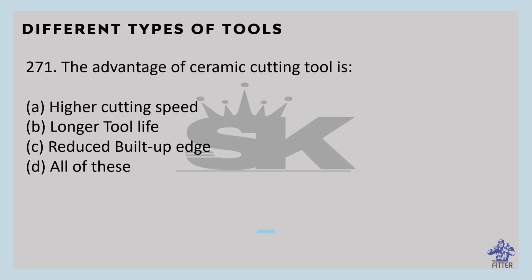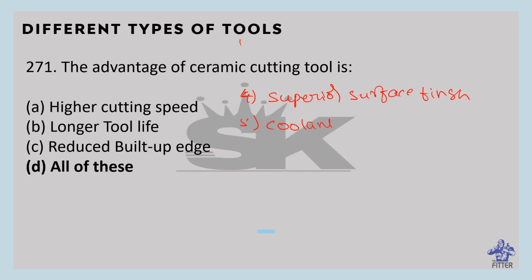The advantages of ceramic cutting tools: higher cutting speed, longer tool life, reduced built-up edge. Few more are there. That is superior surface finish, and coolant is not needed.